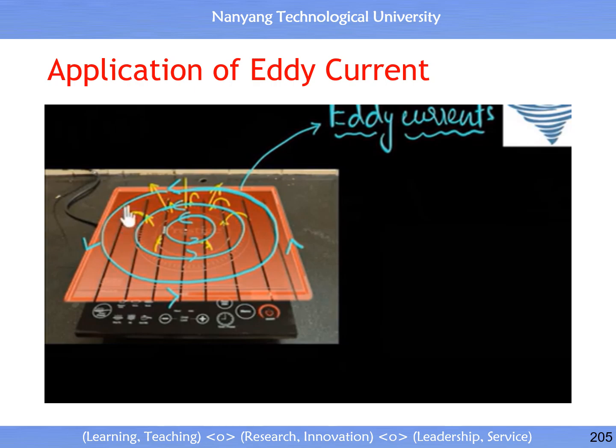We are introducing air in between, and air is an excellent insulator, which means the overall resistance of this now has increased tremendously. And as a result of that, the eddy currents now have reduced tremendously, which means less heat loss. And this also means now there is less area for the current. So you'll have tinier eddy currents. And again, because of this, we'll have less heating effect.